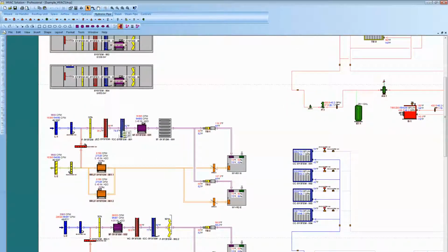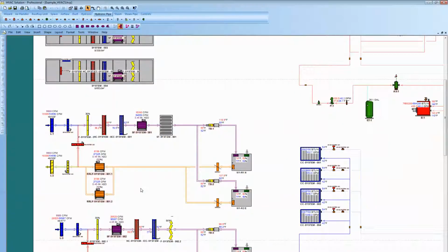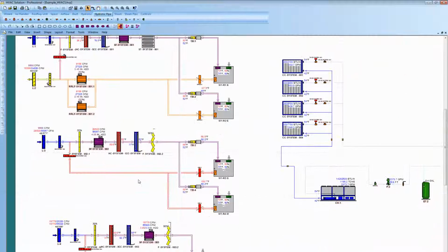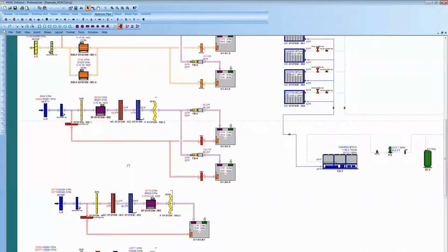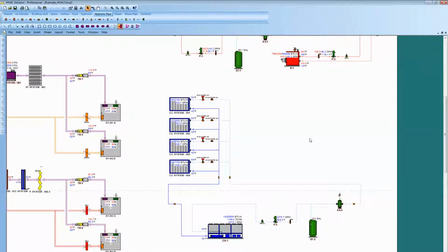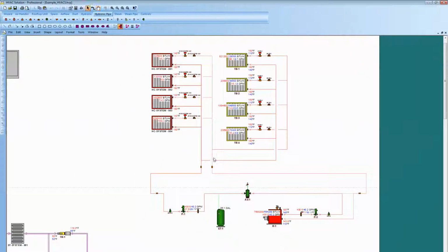Then down below is each airflow wizard, how the fans relate to the space and to louvers and dampers. Remember, we're going to size all this equipment and select equipment, so we need to know all that data in all the different components, louvers, dampers, spaces, so we can do selection of all this product. There's airflow diagrams there, and then over here to the right would be the hydronic cooling generation system and the heating. Now you can see these are the heating coils, and here's the reheat coils.